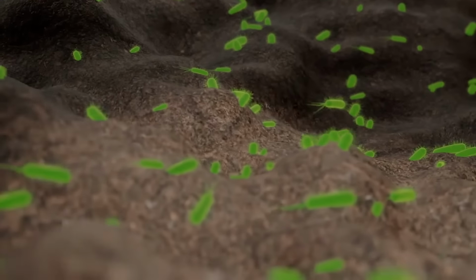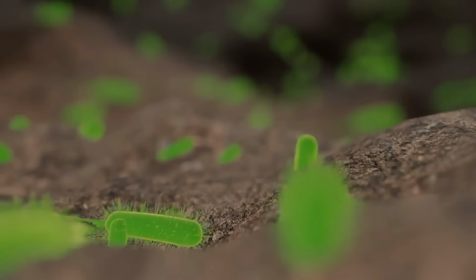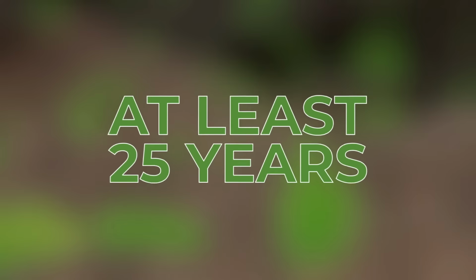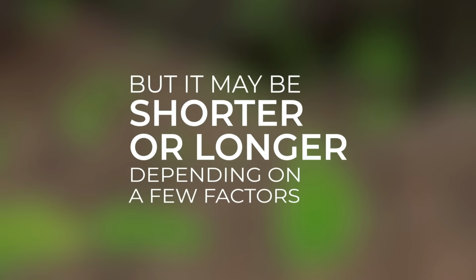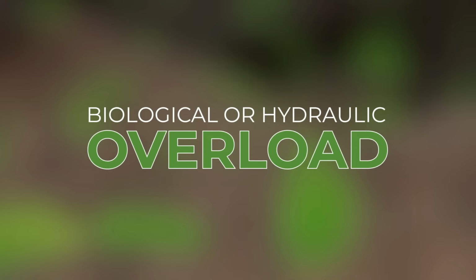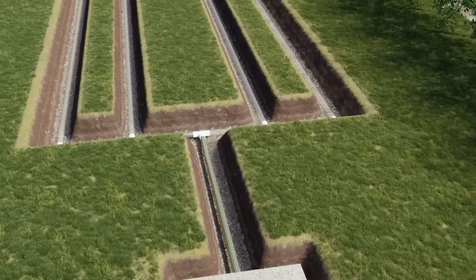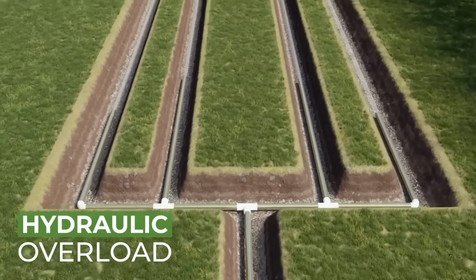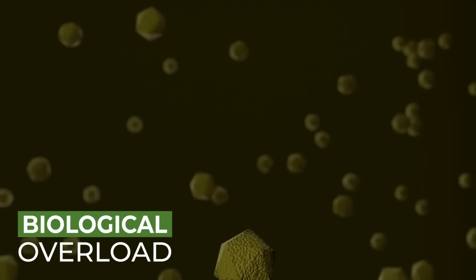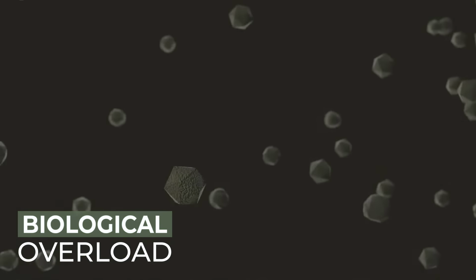This natural purification principle prevents groundwater contamination. A well-maintained weeping bed should last at least 25 years, but it may be shorter or longer depending on a few factors. Most leaching fields fail due to biological or hydraulic overload. Hydraulic overload occurs when too much water is sent to the septic tank. Biological overloading occurs when too much organic material reaches the leaching field.